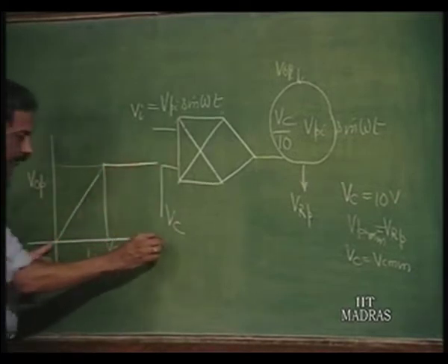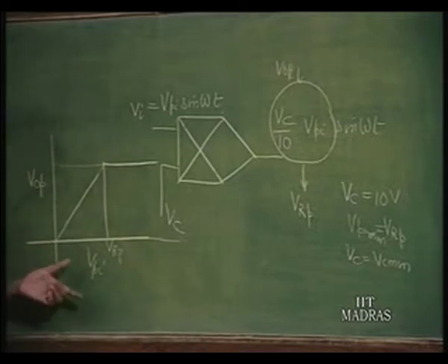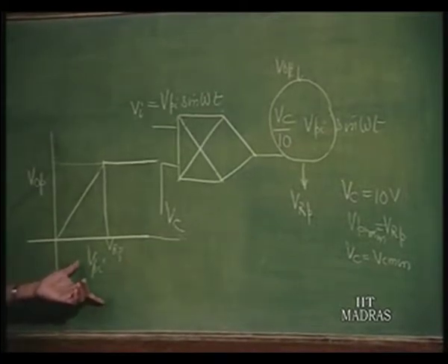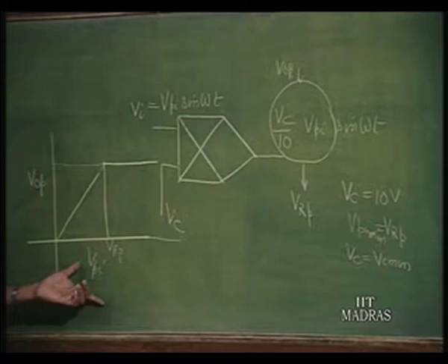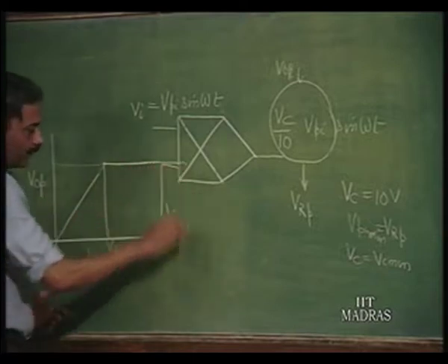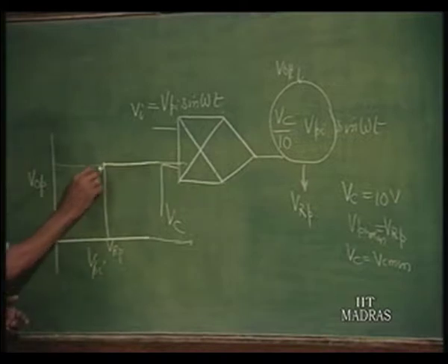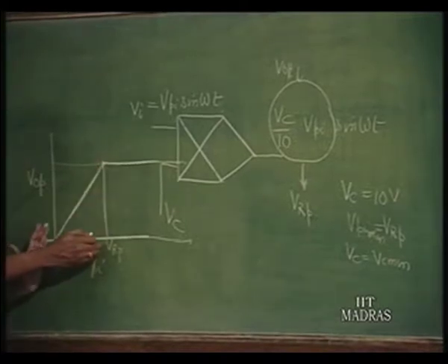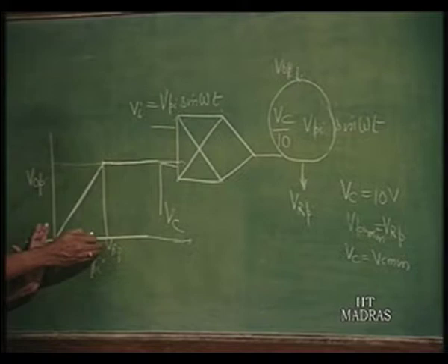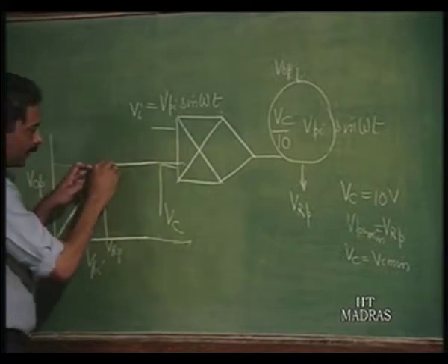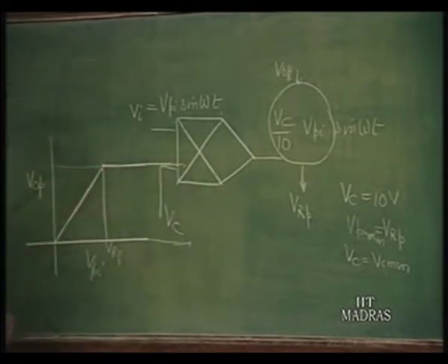Then I should not apply VPI greater than 10 volts for this. So, up to that point the AGC will work. This is the characteristic within which it is simply acting as an amplifier without any control. After this, control takes over and output will remain constant.